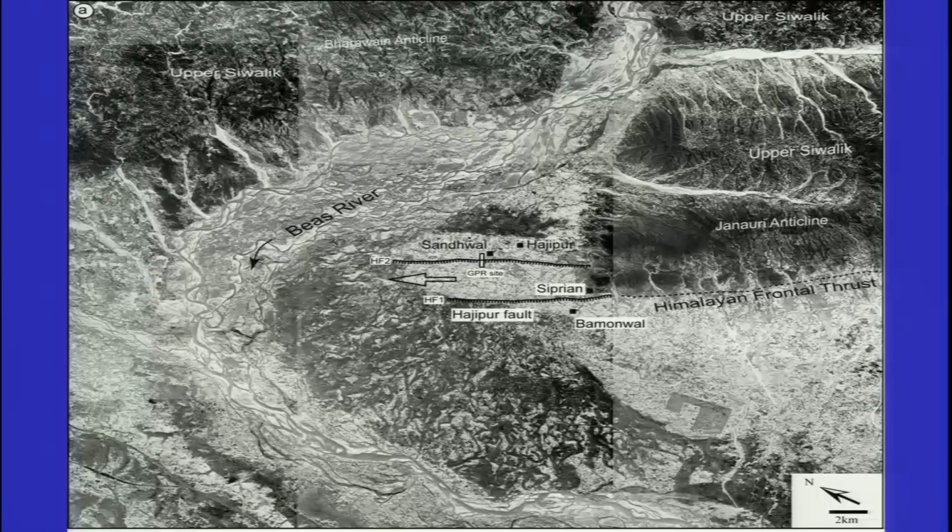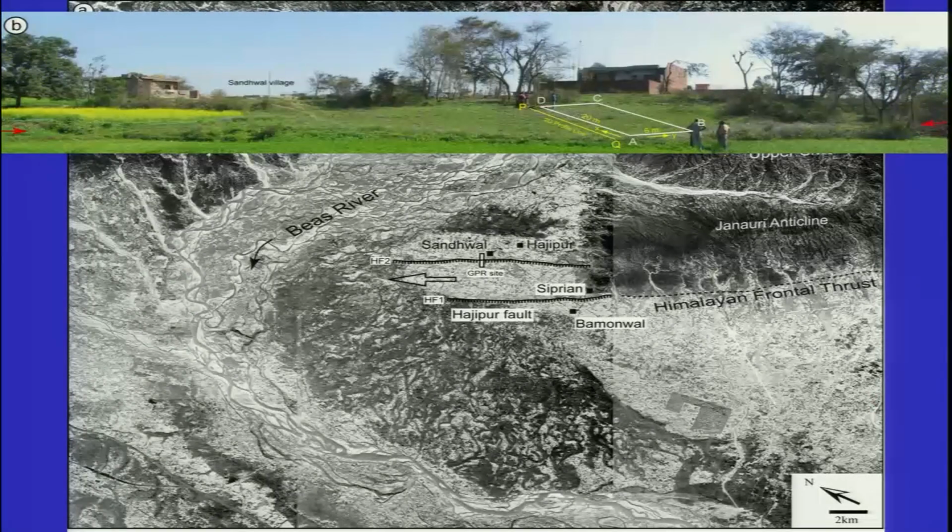So, coming to the area of Beas, at this location here, detailed mapping was carried out using a total station, but we fixed the site after doing a detailed GPR survey in this region. So, using geophysical methods is another advantage before getting into the trenching part. As I have been telling, we use satellite data, then go into the field, do the mapping, and then before we get into the trenching part, we do the geophysical methods.